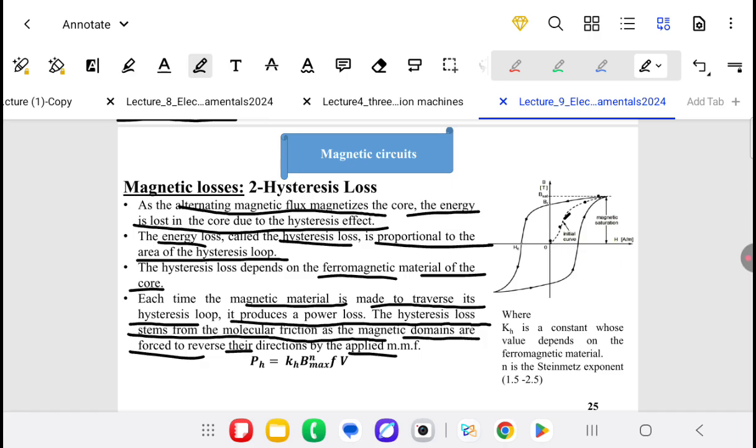As we magnetize the material initially, it begins from flux density and H equal to 0, and by increasing the H or the I, we get an increase in B, as we have seen in the BH curve, until we reach the maximum value of the magnetic flux, or the saturation. The current is in the form of AC or a sine wave. Then from point O to point A, which is the maximum value of the current, we have this point A.